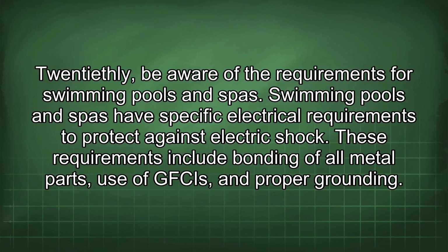20thly, be aware of the requirements for swimming pools and spas. Swimming pools and spas have specific electrical requirements to protect against electric shock. These requirements include bonding of all metal parts, use of GFCIs, and proper grounding.